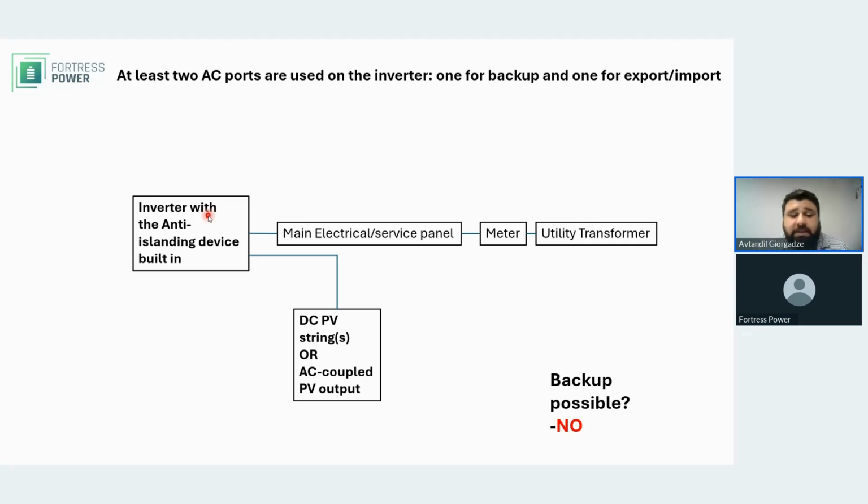Whereas when you're doing the line side tap, it's easier to swap the cable. If it's going to the load, it's one set of cables. If it's going to the grid, it's the other set of cables. Whereas here, if you're doing load side tap, one set of cables and a set of bus bars facilitate all the current flow. And the bus bar being the bottleneck, line side tap would be preferred if you want a bigger installation. I'm not going to go into the details of NEC code.